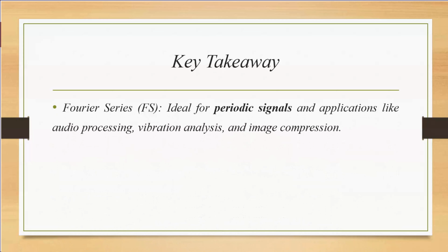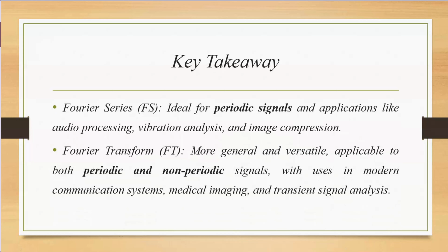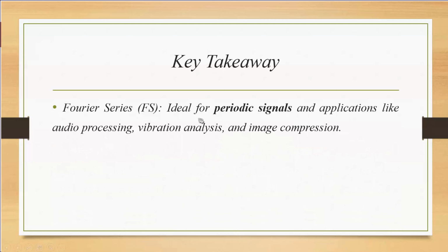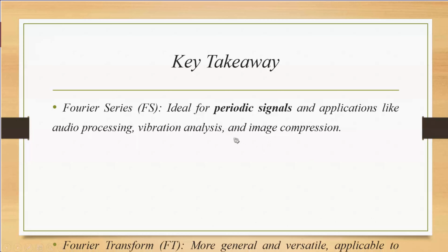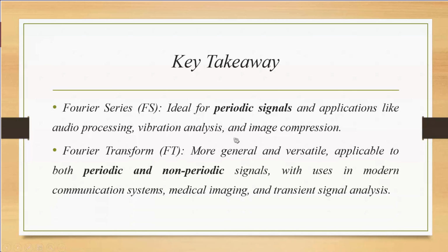So the key takeaways in this discussion, we have seen that a Fourier series is actually ideal for periodic signals and applications in audio processing, also vibration analysis and image compression, whereas a Fourier transform is a more general and versatile tool and is applicable to both periodic and non-periodic signals. Its applications are in modern communication systems, medical imaging, and transient signal analysis.